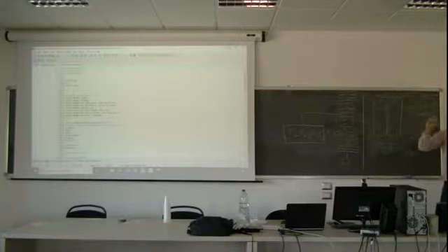So we have been dealing with these equations and applying energy conservation to each node. And then we figured out that if I am in the fin, for example, and I want the temperature of node number 2, if I don't know the temperature of node number 3 and number 1, I cannot get it, so I need some trick. The trick is to make an assumption.